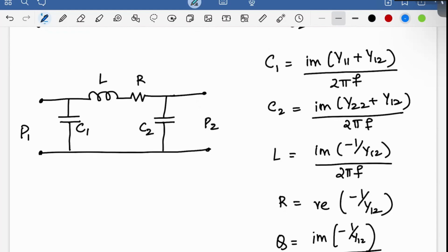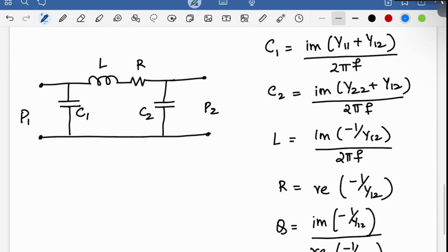Okay, that's fairly good. The thing you need to keep in mind is that this is a circuit model, right? So you need to make sure that the structure you use to extract these inductances and capacitances should faithfully represent this circuit model, and we'll make sure we do that as well. Again, one thing to keep in mind is that the ground is often neglected. So you need to make sure the grounds of the two ports are connected, and there are no parasitics in the ground path, which can actually happen, and we'll see that, right?